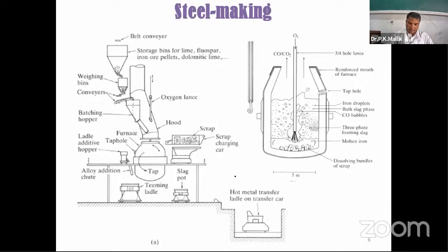The typical mass transfer reaction in a basic oxygen furnace involves oxygen transfer to the exposed metal surface, with simultaneous transport of dissolved carbon from inside the liquid to the gas and liquid interface, and carbon is removed from the melt as carbon monoxide.